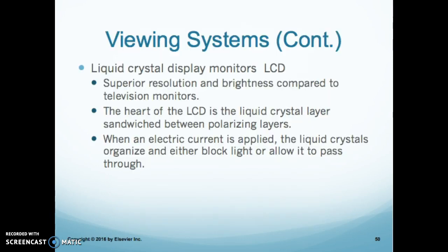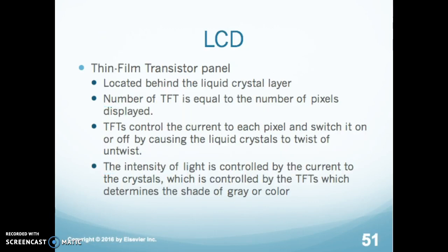When we're looking at other types of monitors, there are the liquid crystal displays, the LCD. These are superior in resolution and brightness compared to television monitors. The heart of the LCD is a liquid crystal layer sandwiched between polarizing layers. When electrical current is applied, the liquid crystals organize and either block light or allow light to pass. And they're thin. The LCD has a thin film transistor panel, the TFT, located behind the liquid crystal layer.